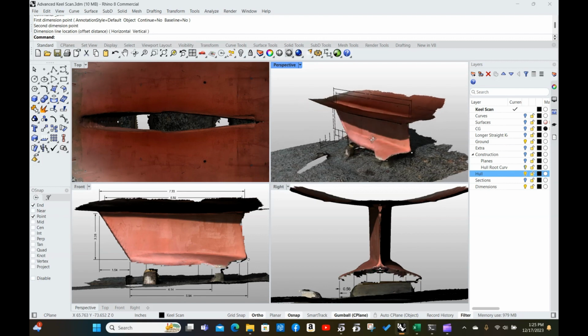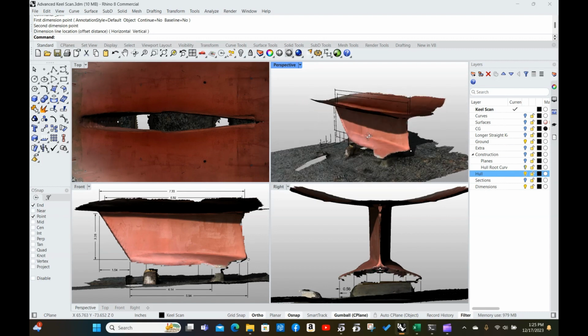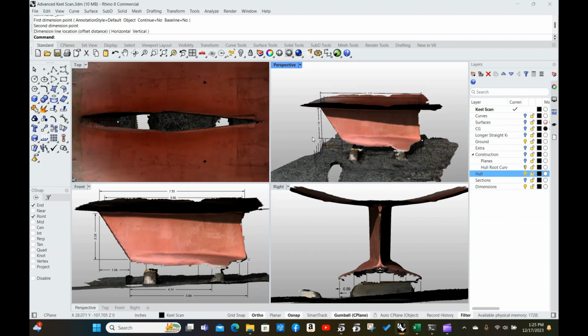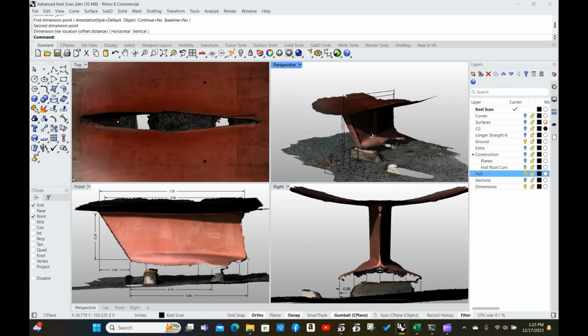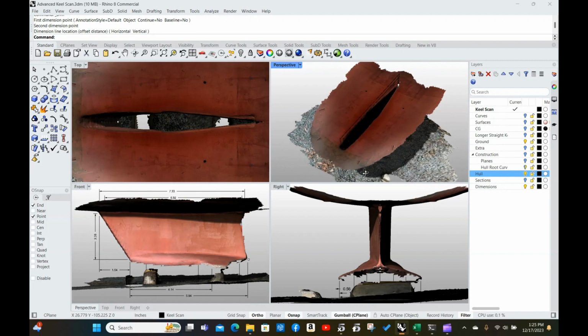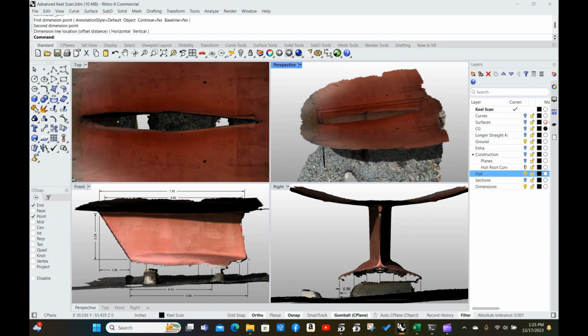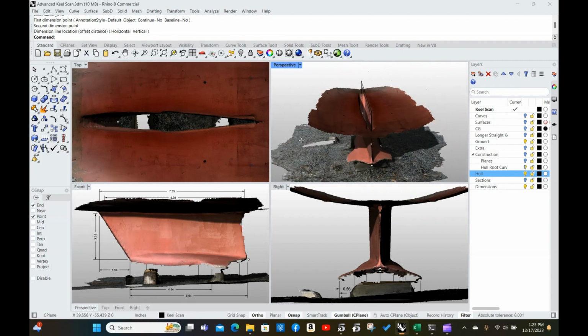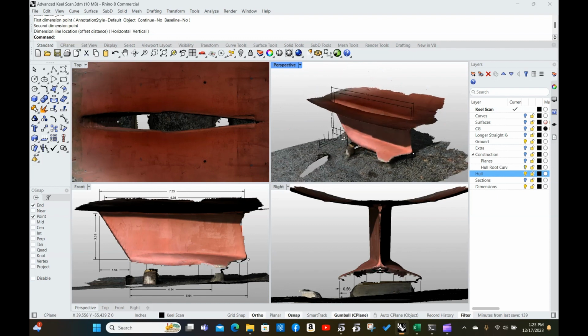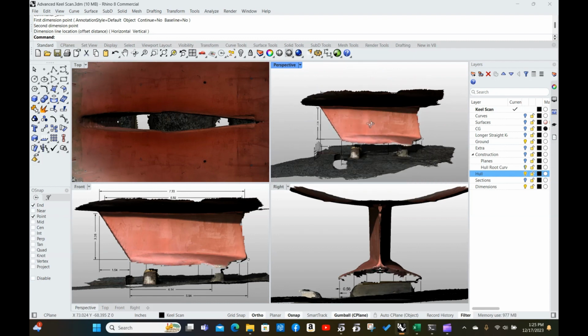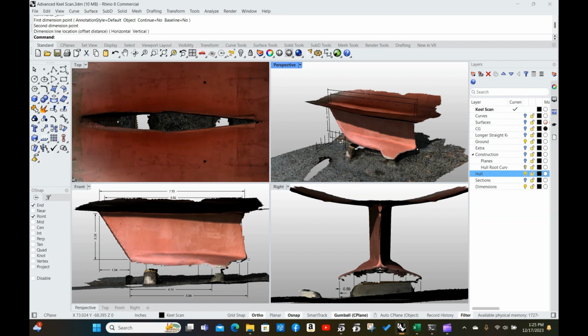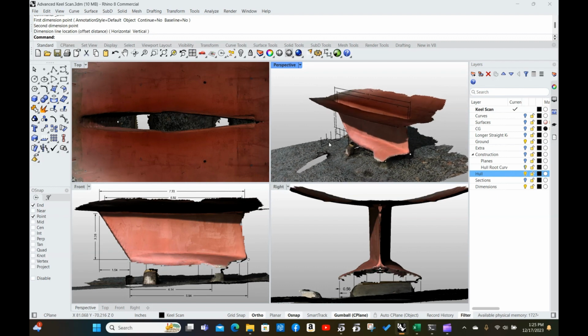I used the advanced LiDAR. It did very well and got a little bit more detail, except it messed up around the leading edge and it was thicker, just like the other one. So I measured the thickness of the keel and all the other dimensions that are shown here, and I corrected the mesh created by the LiDAR.